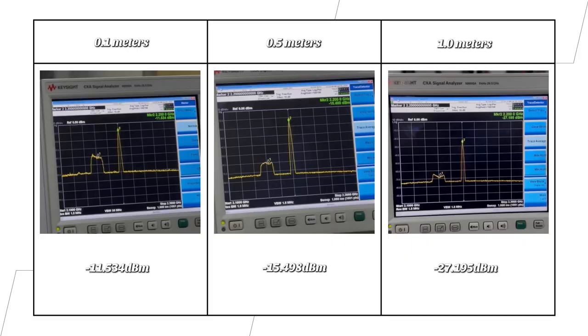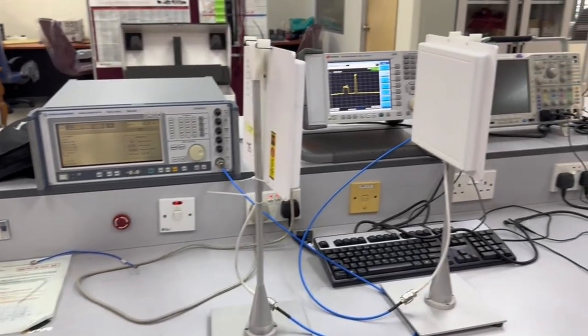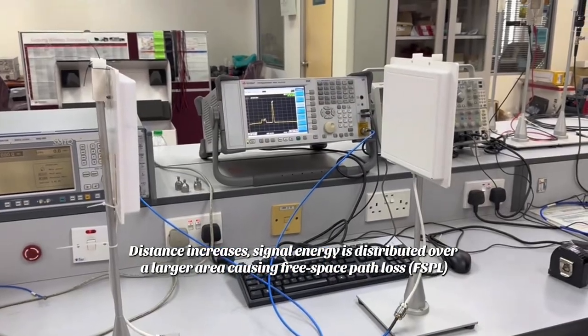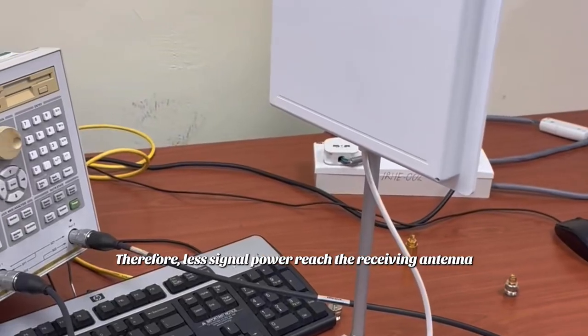From the results shown in the table, it can be observed that as the distance between antennas increases, the received power output decreases. This happens because the transmitted signal spreads out as it propagates through free space. As the distance increases, the signal energy is distributed over a larger area, causing free space path loss. Therefore, less signal power reaches the receiving antenna at a greater distance.